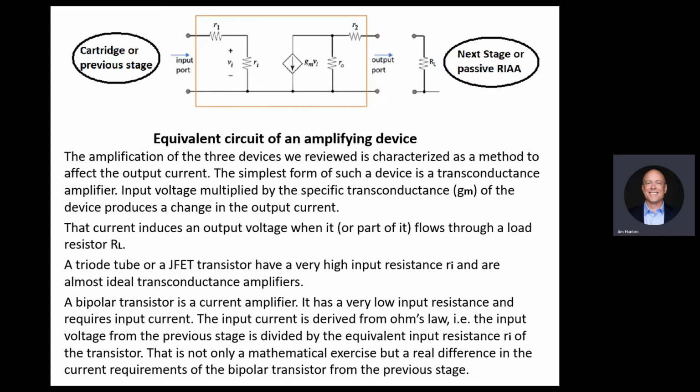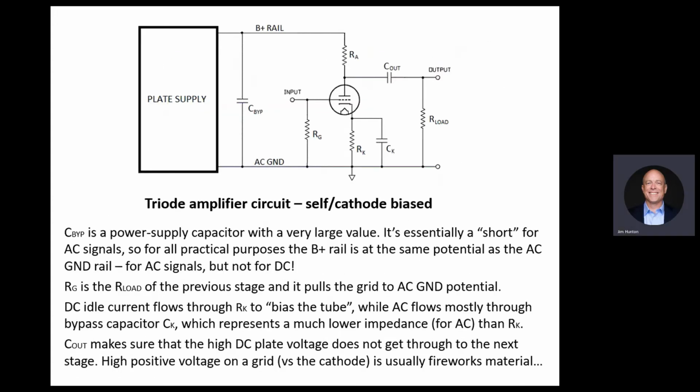Okay, so let's look at real circuits. So this is a tube. We have a power supply. And I think you looked at some of those circuits. So the tube basically is set up with 0 volts here. And we don't want 0 volts on the grid, right? I mean, if we connect the grid to the reference 0, this is the ground, what we call ground. It's a 0 volts for us. If we connect it to 0, we're at the low end of the curve.